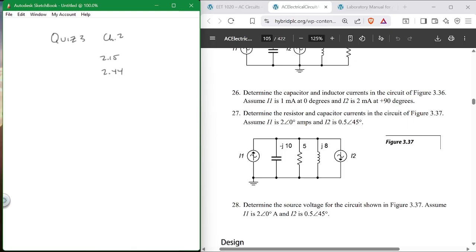The goal is to make this thing go out and come back. You put 24 volts on this, it goes out. It goes to an end and it stops with the limit switch. Then you flip the leads around and put the 24 volt supply on the other side, and what does it do? It goes the other way. So I want you to automate this so it goes out and back and out and back, and keeps doing that as long as I put power to it. That's what I want you to do.